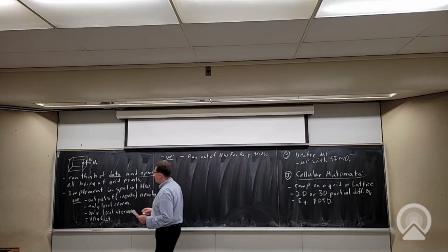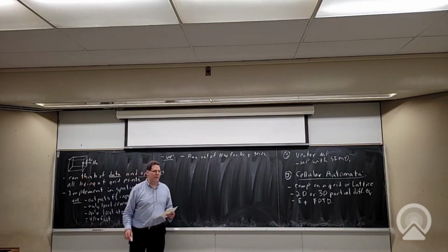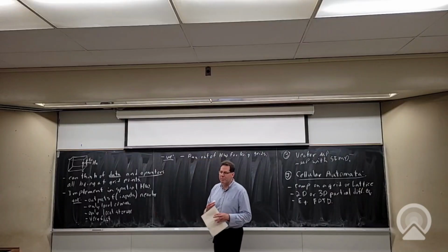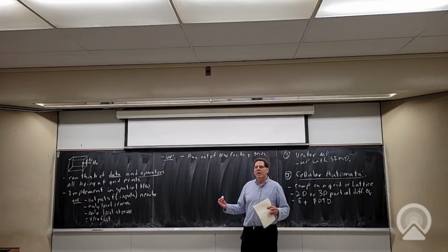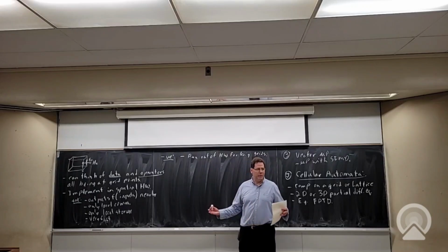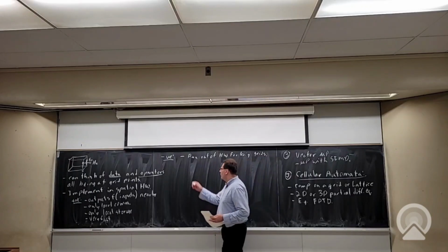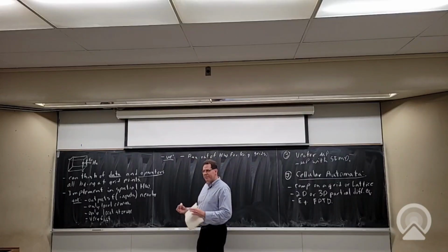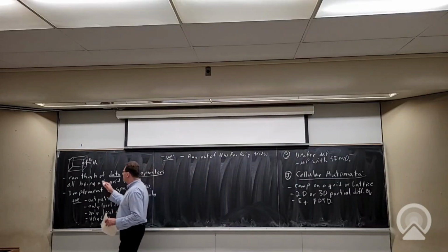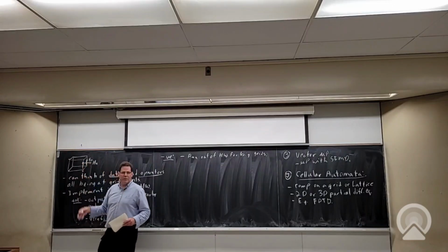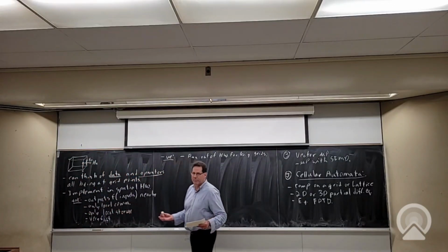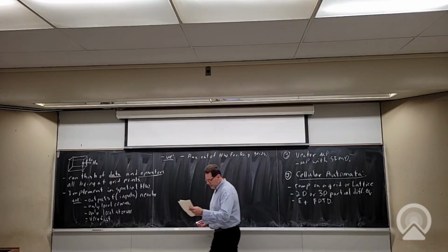And especially in 3D, these grids can start getting big pretty fast, right? People care about the cases they really want to make fast. Not always, but usually they are pretty big grids because they take a long time. And our challenge is that it can start taking so much hardware if we make a different compute unit for every one of these grid points that it just exceeds the size of our chip. So that's a problem.